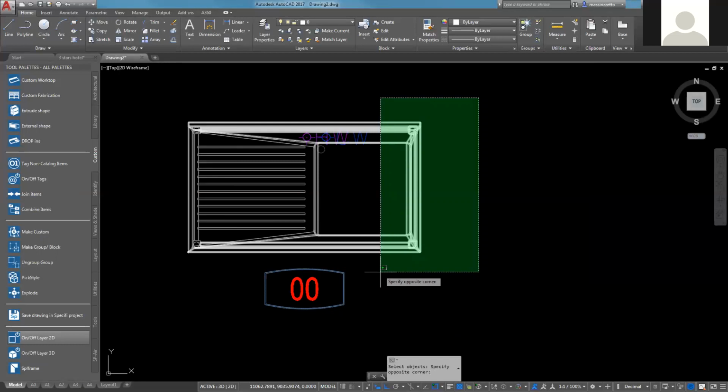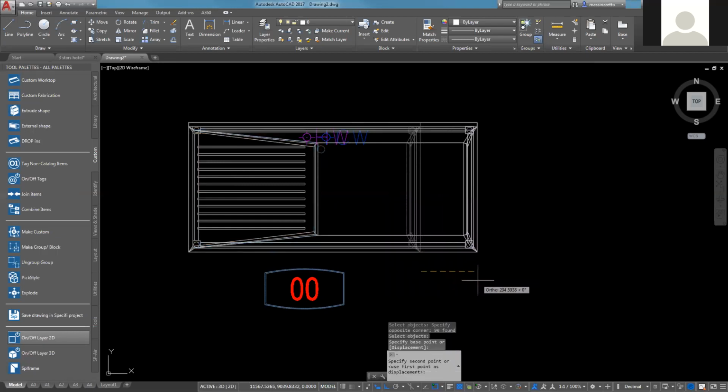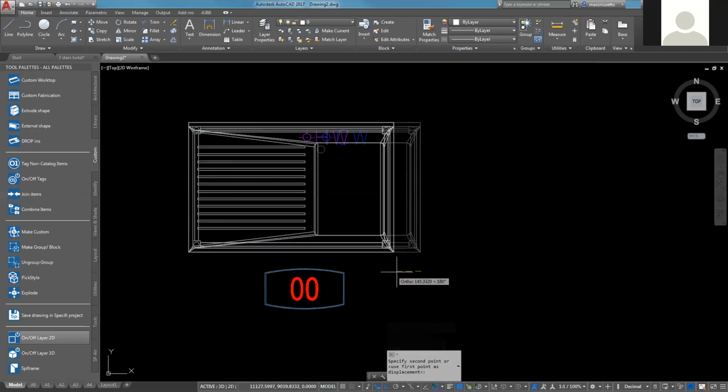So on the left side, you can see that the legs are completely selected. The objects which are not completely selected will be stretched. So I can identify a second point, right-click to confirm and end the selection, and now the base point. I click a point, and with the mouse I give the direction, I can increase or decrease.